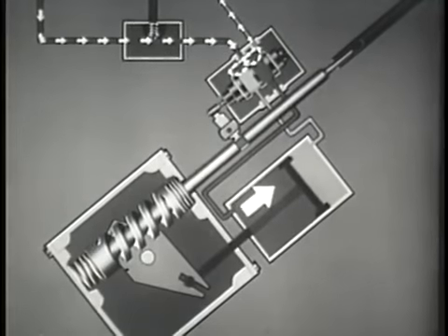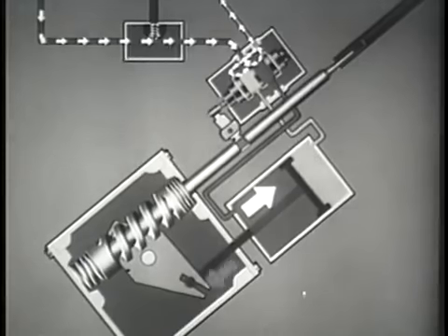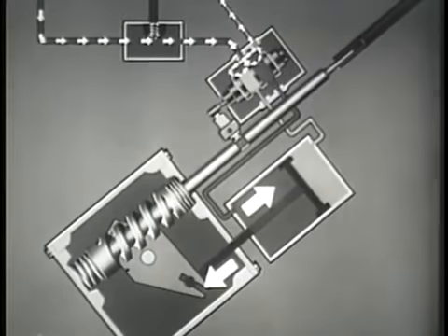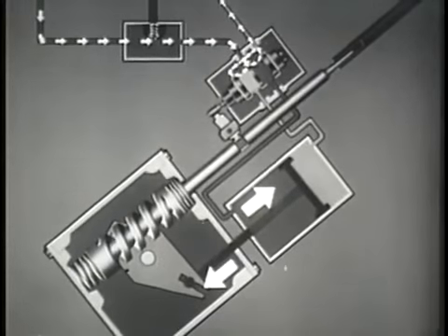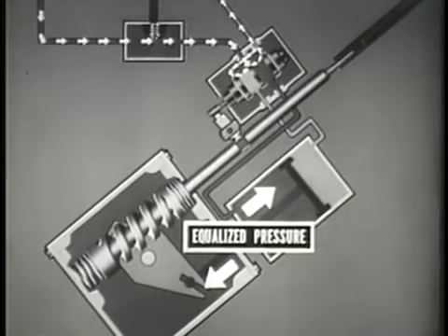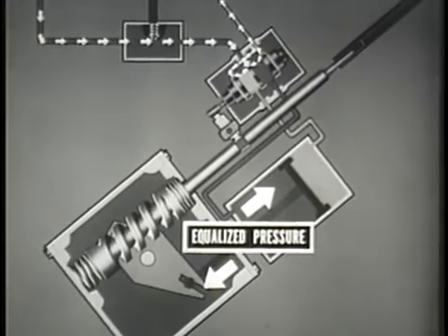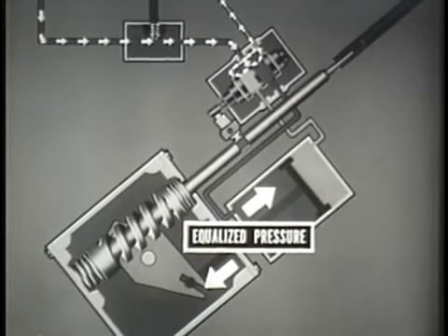This also moves the control valve linkage and positions a valve spool where fluid pressure will equalize the force exerted by the steering geometry acting on the piston rod. The front wheels can then be held in any desired degree of turn.